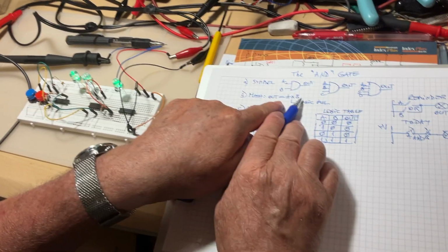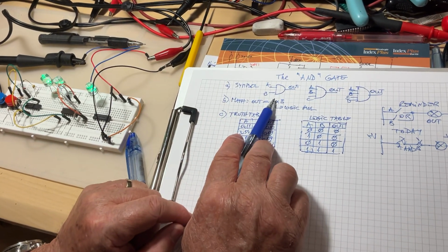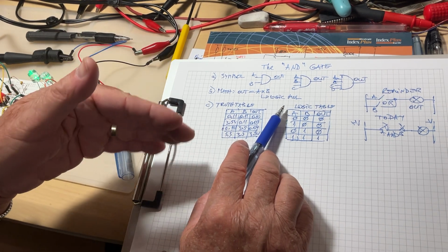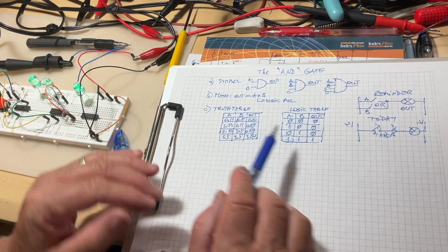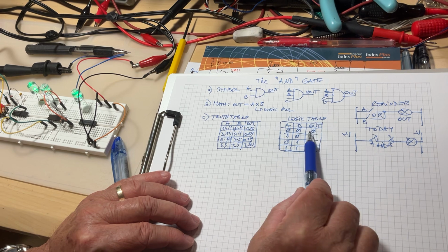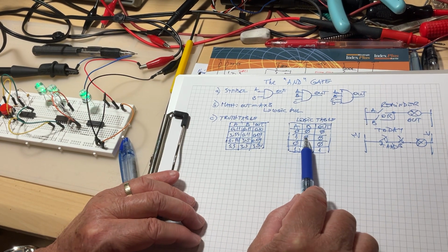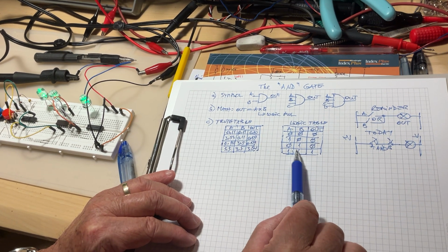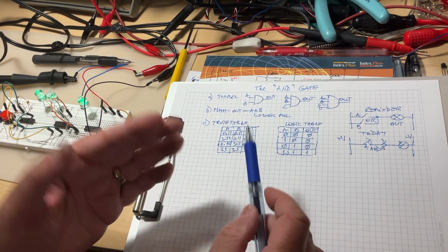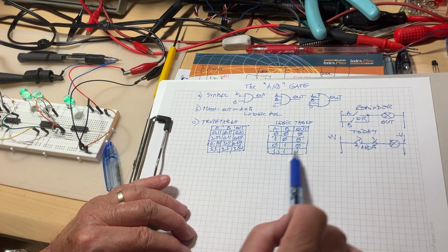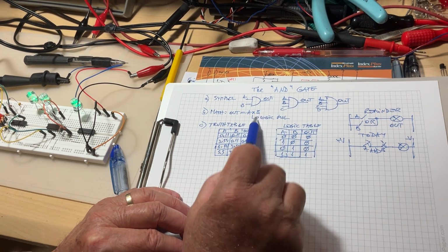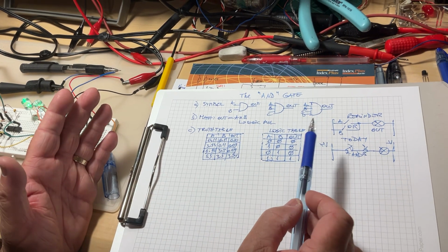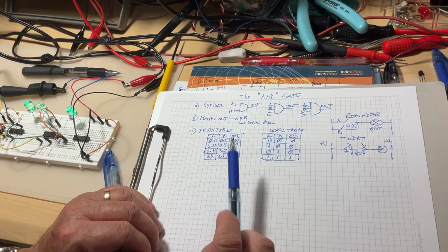Now let's check the formula before. It should be a multiplication. This is one of the rare logic operations which is identical to the arithmetical one you do on your pocket calculator. So here, 0 times 0 is 0. Perfect. 1 times 0 or 0 times 1, they are both zeros. And only when both inputs are 1, 1 times 1 is a 1. So we can check that the truth table we obtained, the logic table, is exactly following the math, the formula for the AND gate. So far so good?